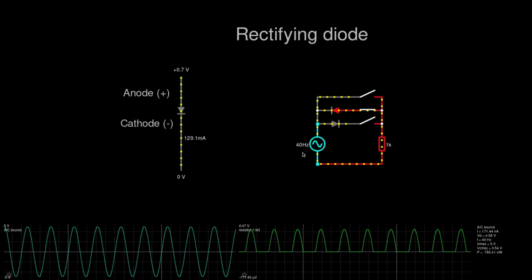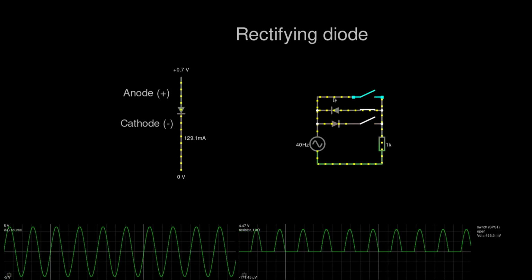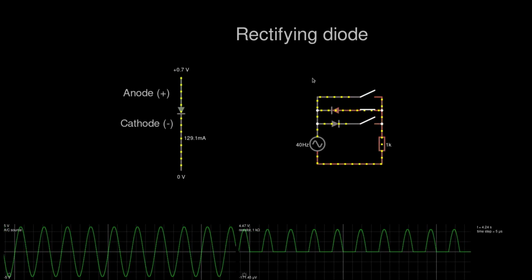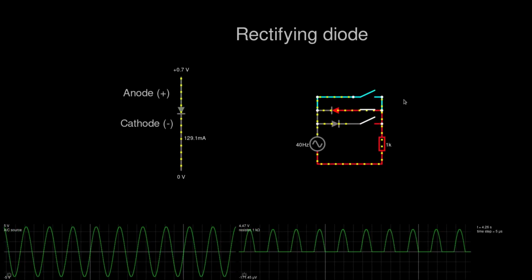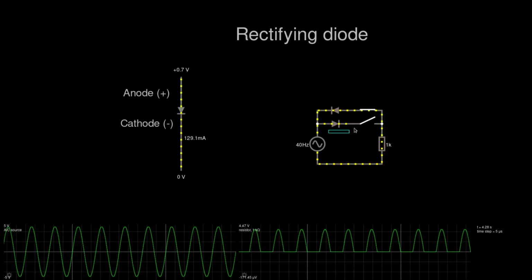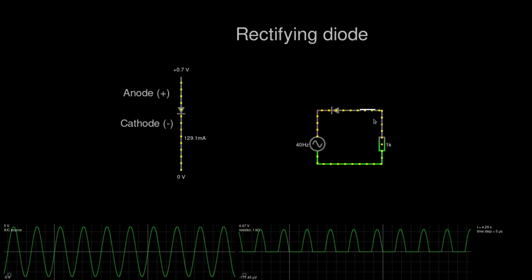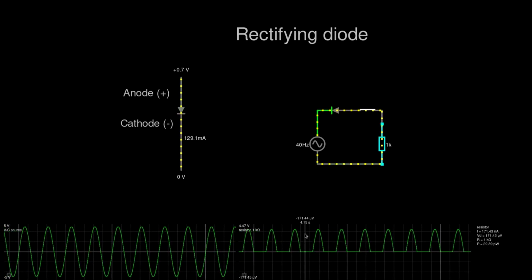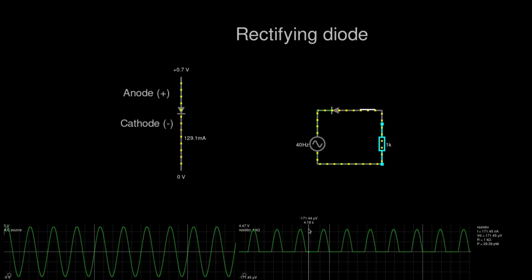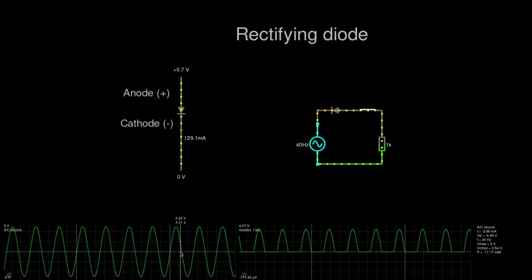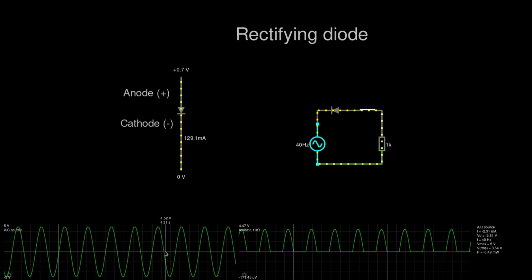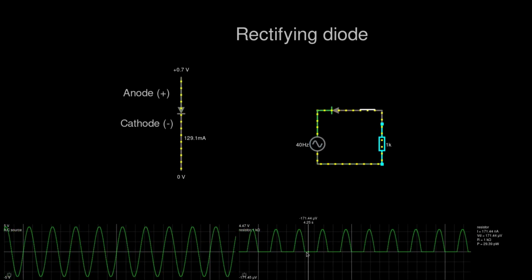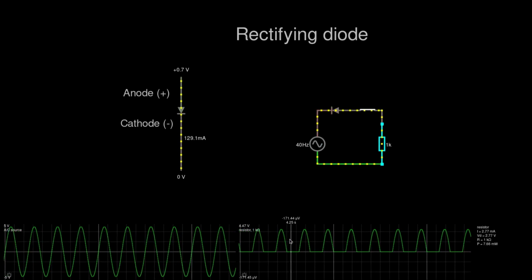By the way, this simple schematic over here is called a half-wave rectifier. Basically, if I remove additional stuff, it's a proper half-wave rectifier. A full-wave rectifier would also take the negative side and flip it upside, so we would, instead of these zeros over here, have another positive side.